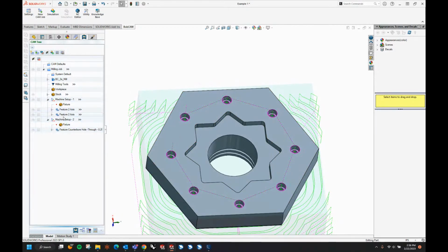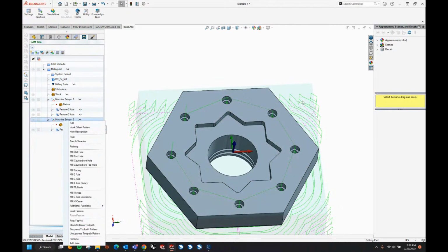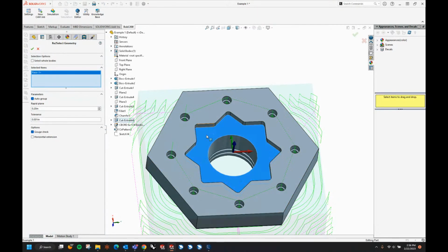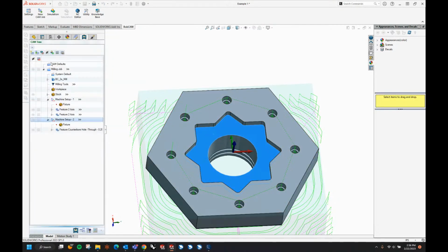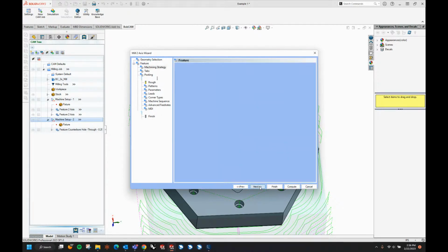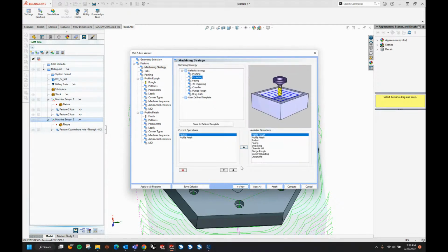Now from this side, I might want to mill out the whole entire outside shape, maybe this pocket. So let's start with the pocket. So I'll do mill 2 axis. And if I just pick that star shape, it should have everything I need. It should know the depth, the shape of it. I don't see the island in the middle, so we're good. We're doing pocketing.